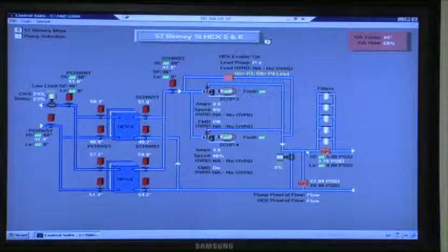I'll find out if we have to get this graphic, and maybe I'll ask you, Robert, to do this because you have the graphic screen on this. Find out where the city water bypass was plugged into this. It might be somewhere in here, or right over here. Then we can do a bypass from city water to drain, so you understand, in a complete catastrophe you can open up city water and go to drain. I think the drain is actually down in the MRI second floor. So you go up and open the city water, close off the chill water, go below and open it to the drain, so it runs through the piping all the way downstairs and drains out the bottom. I'll get that information, because it's good to know.